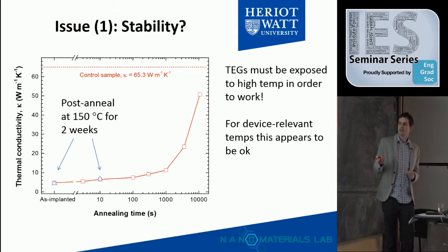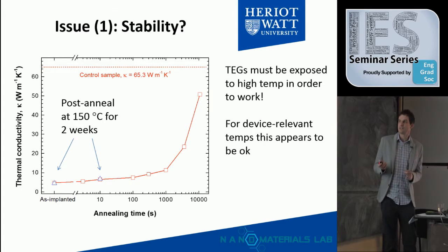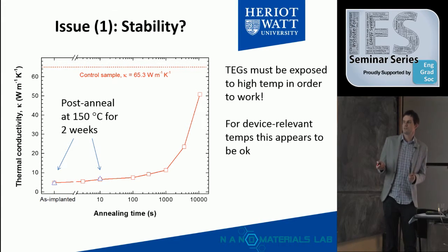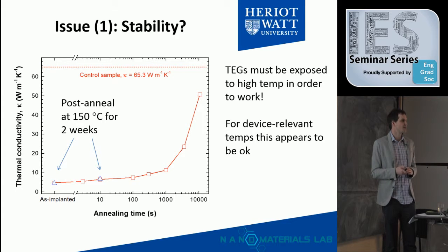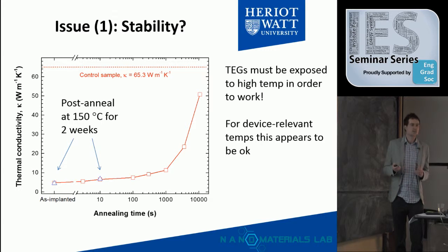And what we've done, when we take these optimal samples, these as-implanted ones, and do some post-annealing on them, so we put them in a furnace for a couple of weeks at relatively low temperatures, we don't see any difference there. If you go to higher temperatures, then you do see a lot of evolution of the defects. If you stay at low ones, things seem quite stable, at least for 2 weeks. So that's promising so far.